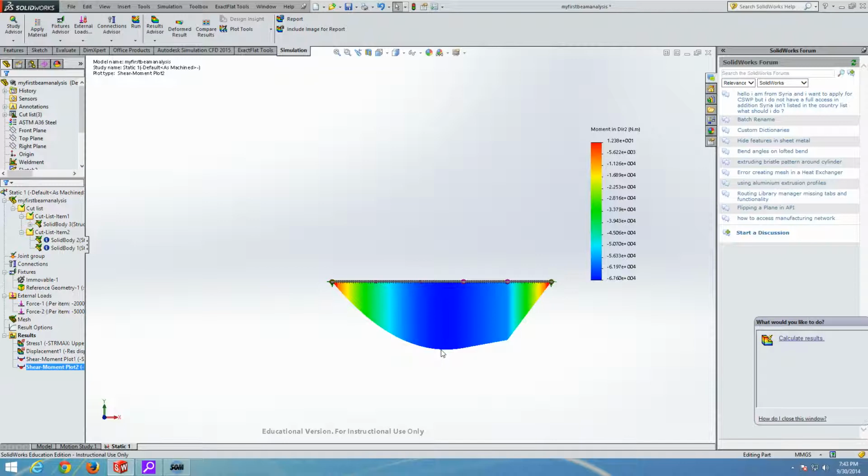Now you should start making your own analysis from the assignments that are on Talonet, and the process is exactly the same. Use any rectangular profile, it doesn't matter which profile it is, because those are all statically determined models. So be sure that you don't use a circular pipe, because then you will have no way to know which is direction 1 and direction 2.